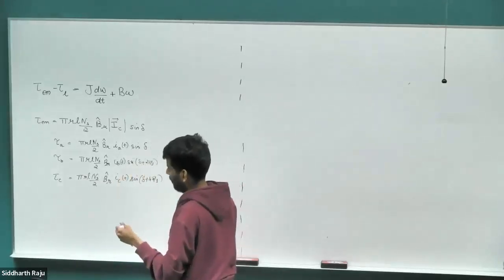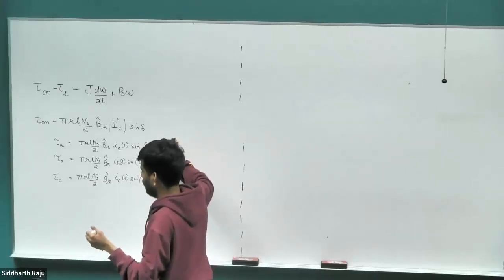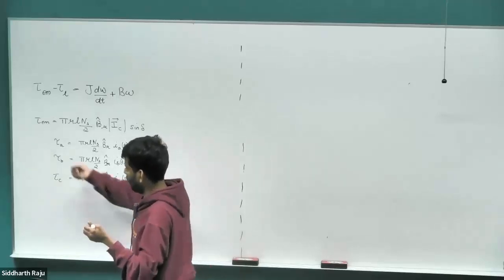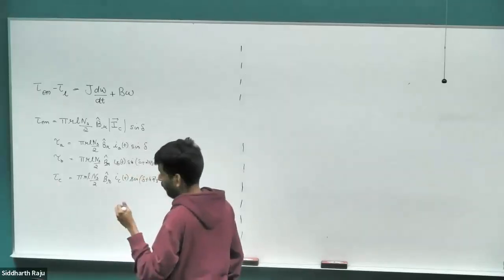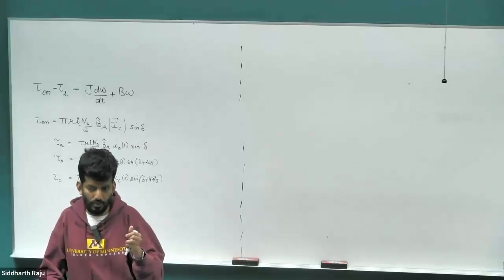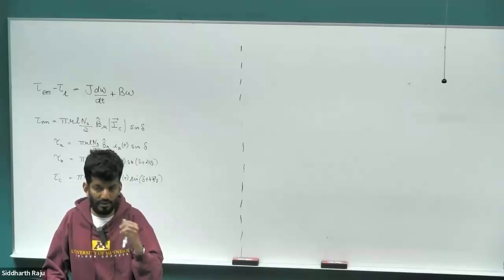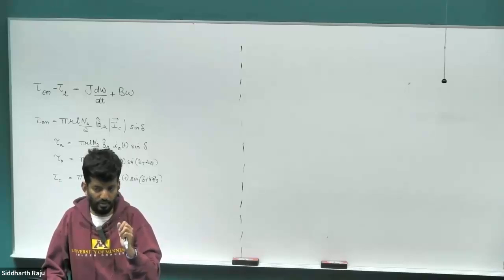That's why you don't typically see a permanent magnet synchronous motor that's one phase, because if you are willing to spend money on putting a permanent magnet on the rotor, then you should have money to put 2 more phase coils and make a proper motor. Okay. When you do an induction motor, that's not the case. You do make very cheap induction motors where you don't want the extra added cost of putting a magnet on the rotor, and you just use these copper or aluminum rotor bars. You don't even put copper because copper is slightly more expensive.